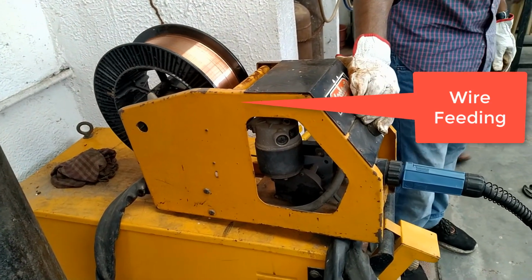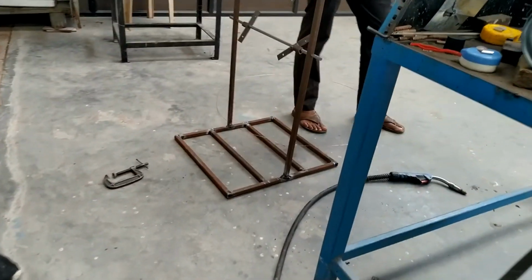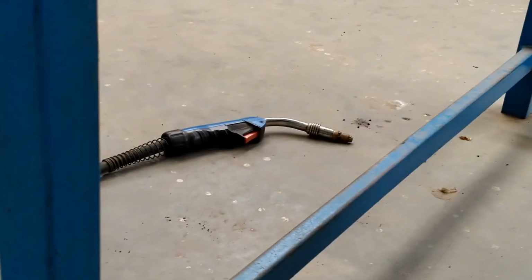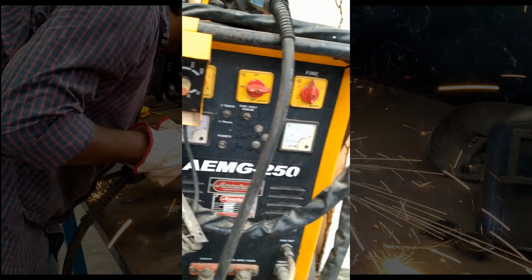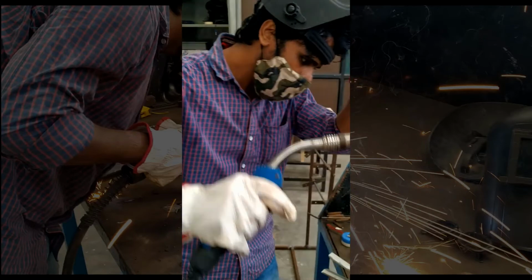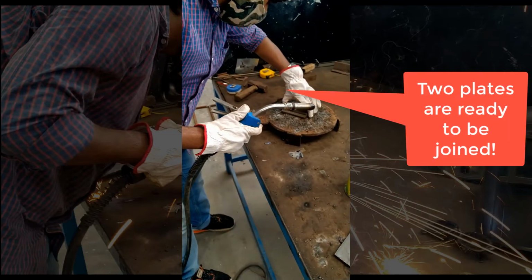When we switch on our setup, your wire is continuously feeding in our electrode holder, or we can say our welding gun or welding holder, right? Just by switching on our setup, the motor will start, and due to this motor your wire is continuously fed inside the system. So now we are ready to start our welding.